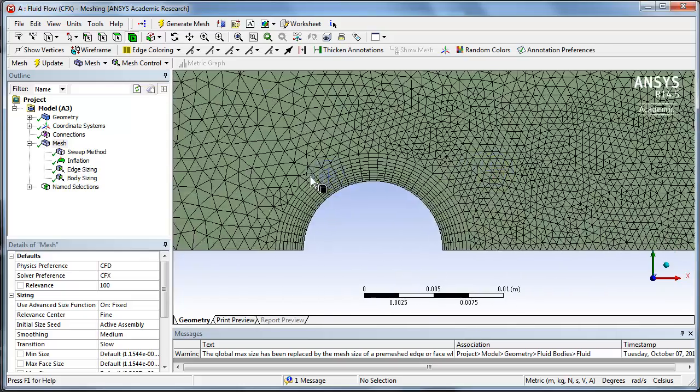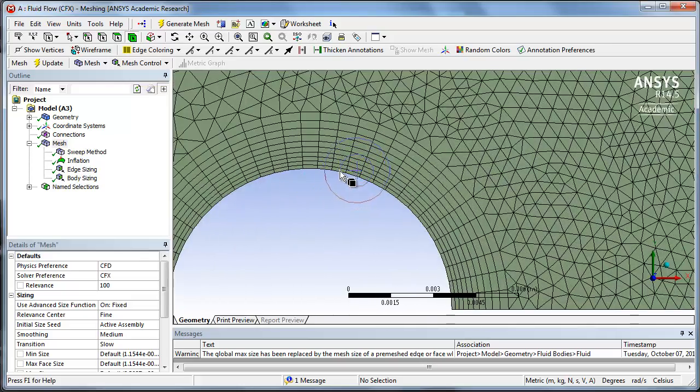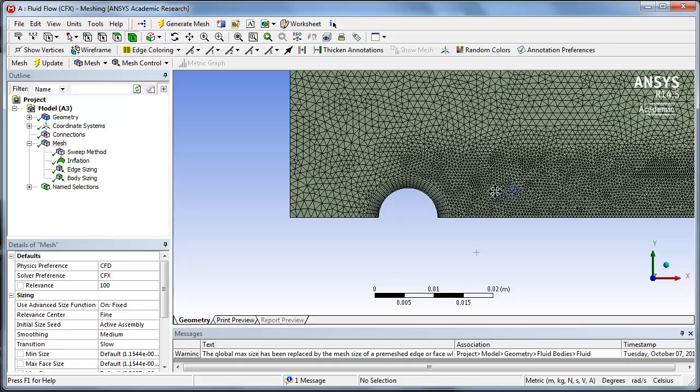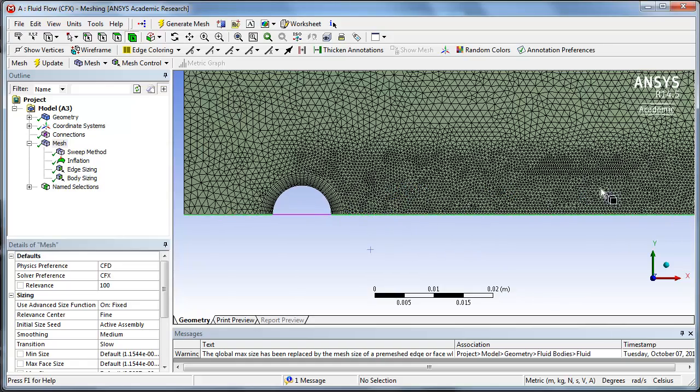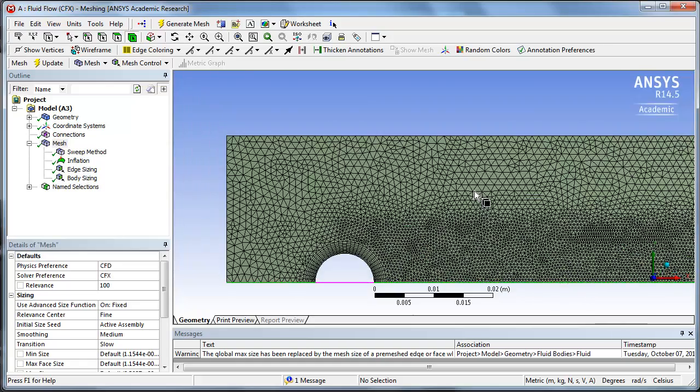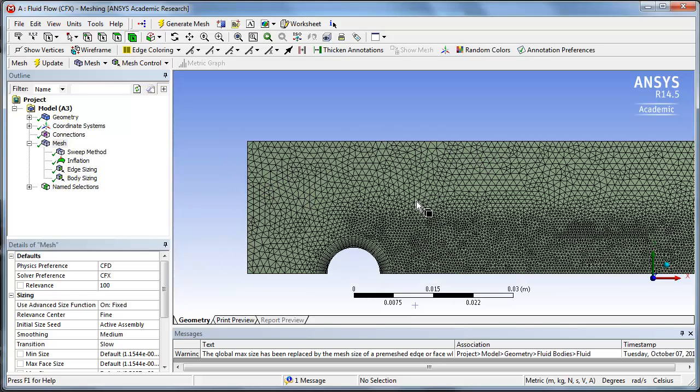and workable for us. So we see that we have a small mesh at the surface of the cylinder, which is what we would like. That expands uniformly. There are no large discontinuities. And in the region behind, or in the wake of the cylinder, I have a finer mesh. Further away, where I expect not much to happen, I have a larger mesh.